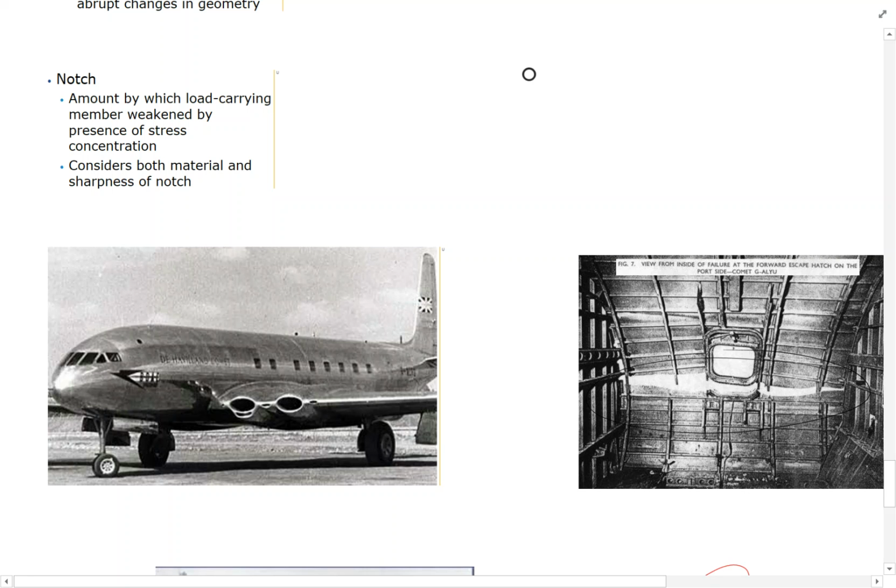Absolutely true story. I mean, this goes back to the 50s probably. This is a company called de Havilland, and at the time they were the leading manufacturer. They were the Boeing of the day, if you will. And somebody didn't really pay that much attention to stress concentration factors, and they made the airplane with square windows. What do you suppose happened to those airplanes? They fell out of the sky. I mean, seriously, like multiple crashes. They went out of business. They no longer are around. So there's your lesson: don't design an airplane with square windows because you too will go out of business.